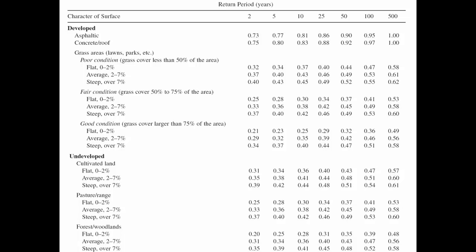I'm just really guessing here, and I'm looking at different descriptions of things, like a poor grassy area versus there might be some buildings in a rail yard. Let's just use a C value of 0.6. And that's not the right answer. That's just what I'm assuming. And so I'm going to put assume as a reminder to myself that you can go back later and change assumptions. If the answer you get seems unrealistic or if new information comes to light, you can update your assumptions later on. All right, now with housing, housing is going to be a mixture of grass and roof area.